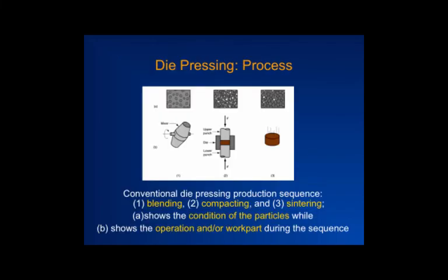Okay, so what you do is you take some powder and blend it with a solid additive. Zinc stearate and ethylene bisstearamide are some possibilities, and you blend them together, right? In some cases, as in making some kinds of ferrous materials, you might blend the iron powder with some graphite powder. Maybe you might add some nickel to it, things like that, to change the properties of the final mixture. And then you pour the powder into a die, which is basically a hole.